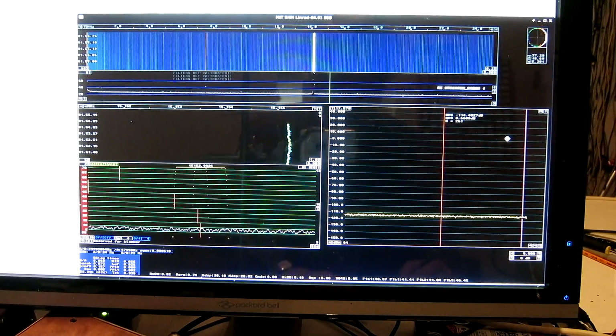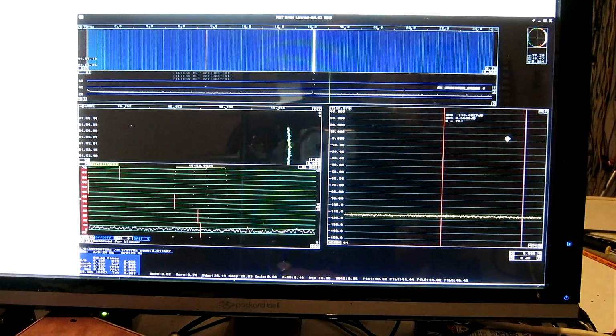When sampling at 200 megahertz I had 149.9. So it means there is about 6 decibels degradation of the noise floor, which is in accordance with theory, sampling 4 times slower.